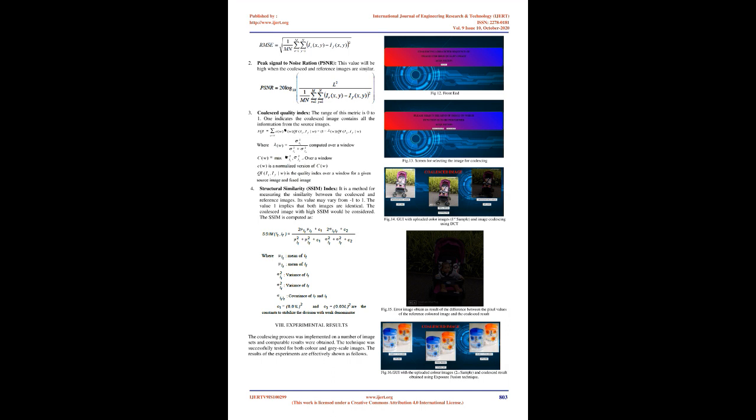Signal fusion is performed at both levels independently. Background signals, obtained as the direct product of the average filtering, are combined using an arithmetic fusion approach. Foreground signals, produced as the difference between the original and background signals, are fused using a simple pixel-level feature selection technique. Finally, the resulting fused foreground and background signals are summed to produce the fused image. The SEMIF fusion system is shown in Fig 8.